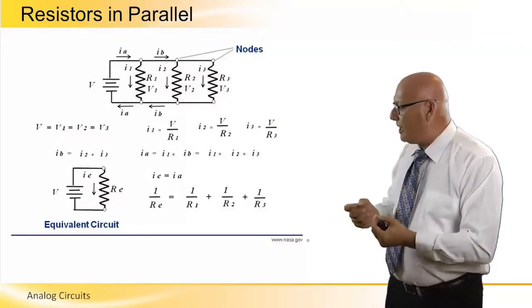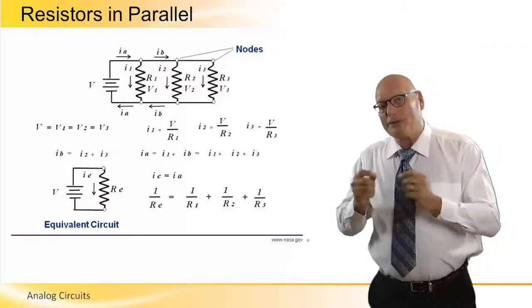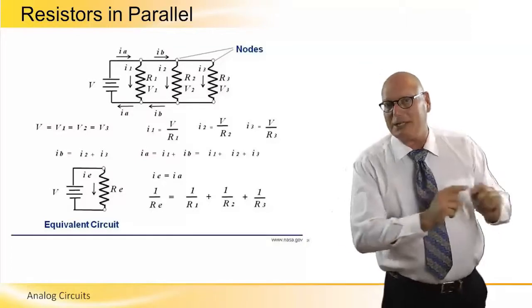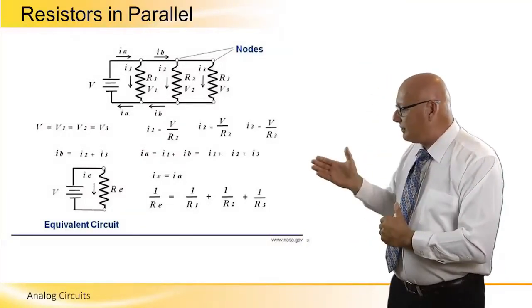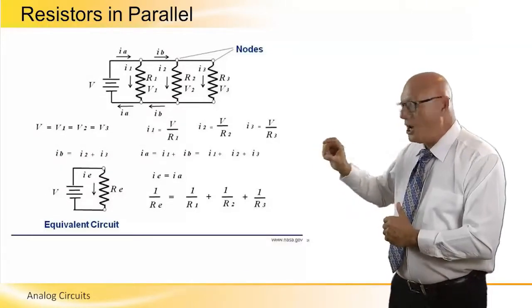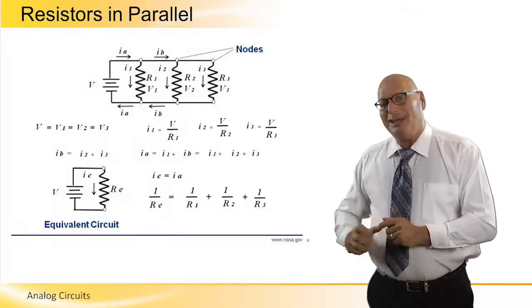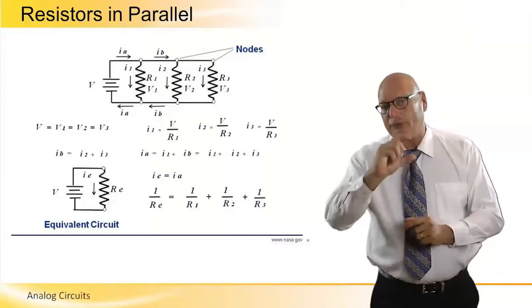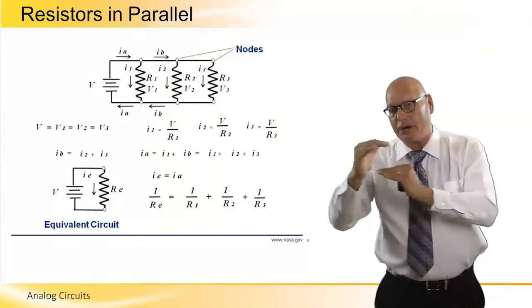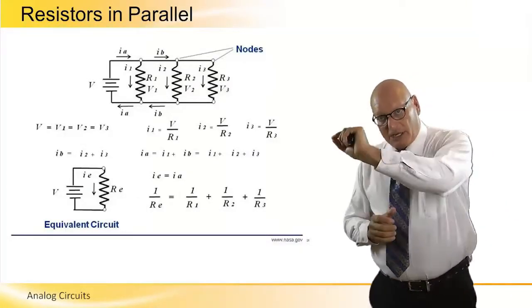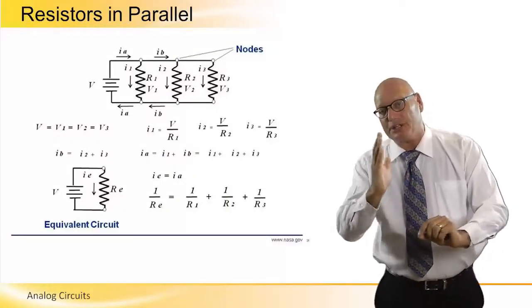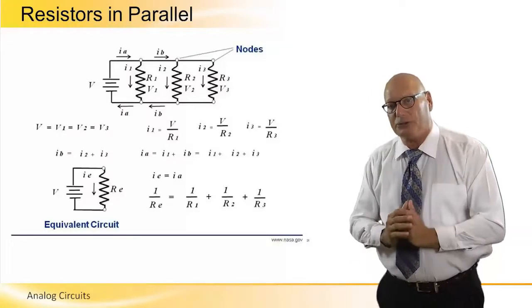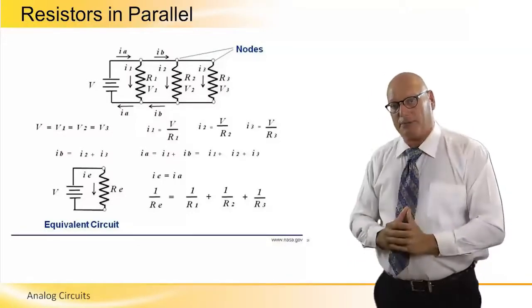And if we apply Ohm's law now, just at a top level, before we even study that, we can see that the voltage across each resistor is equivalent to the voltage of the battery. They are all in parallel. There is a short on the top and a short on the bottom, and the resistors are connected in parallel to each other and in parallel to the battery.